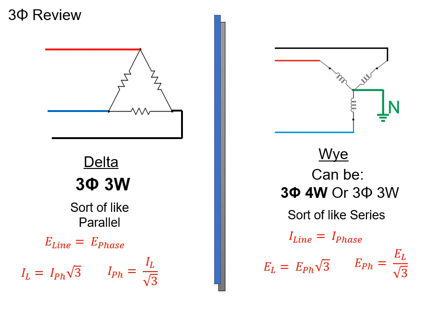If my loads are the same and the system is balanced, then my phase voltage will be smaller than my line voltage by a factor of √3. If we wish to calculate our power in our three-phase system, then our total power is equal to √3 E line I line, or equally we can calculate it by our total power is equal to 3 E phase I phase.